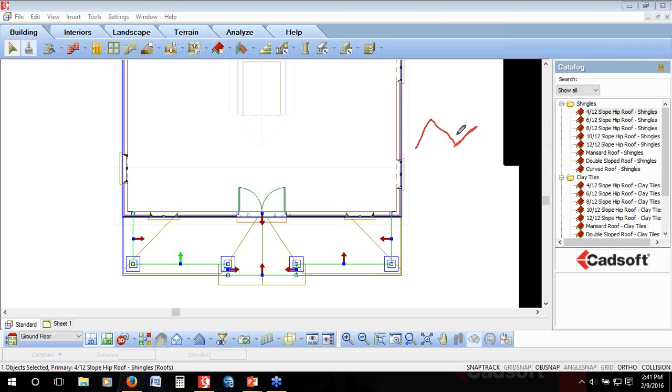It's this area right in here that I worry about. If you're in an area that has high levels of rain or a snow load coming down on that, that's where there's going to be buildup and drainage issues. You could create, obviously, a downspout in there to funnel the water, but the roof surface that you have there is going to really wear down eventually because it's sitting there before it drains. And if it's a heavy rain and it takes a while to come down that downspout, that's where he's going to have an issue.